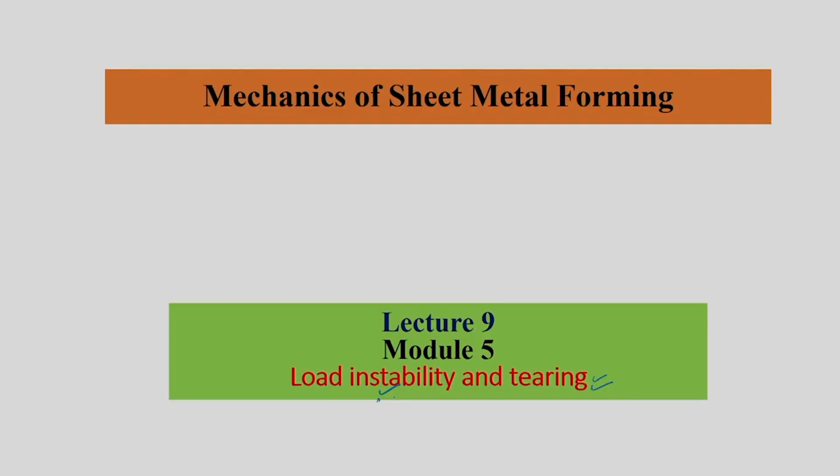So when you deform a sheet beyond uniform plastic deformation, we start with zero deformation and then we cross the elastic portion and enter into plastic deformation. Wherever the transition happens, you have the use of the yield locus or yield surface to know the onset of plasticity. Then we have a very nice uniform plastic deformation in the strain hardening region described by any power law we have used. And then we are going to reach a deformation stage where instability is going to start.